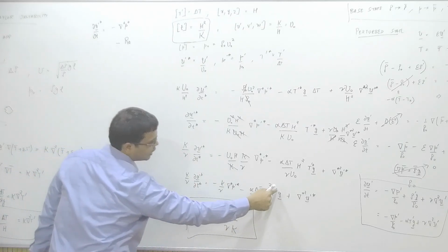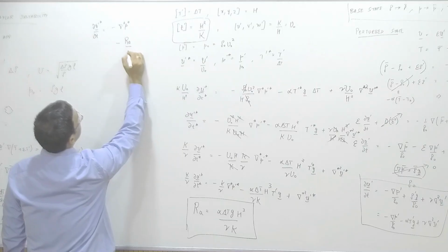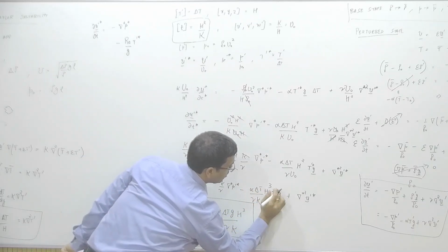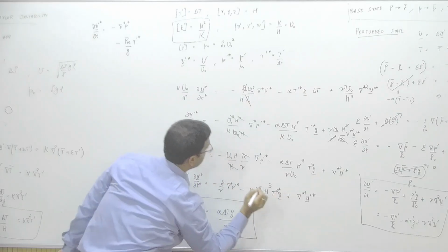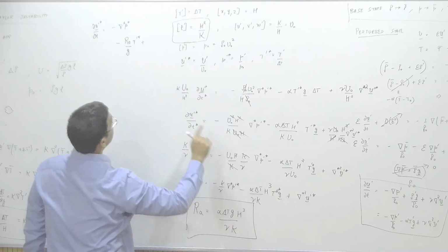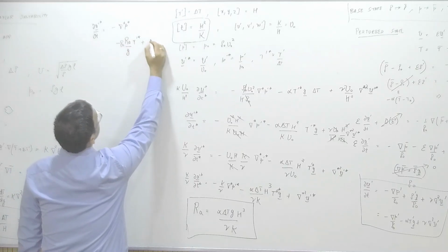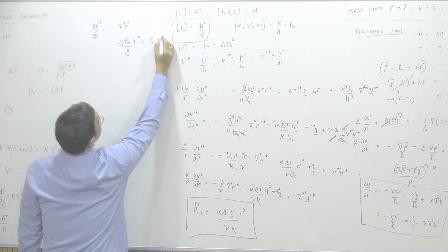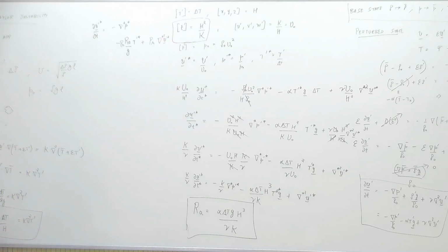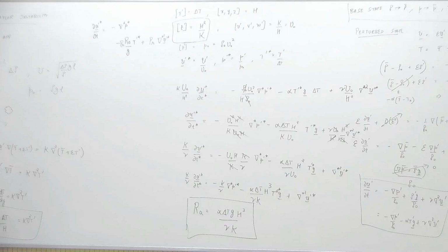Okay, so technically this term that you see here is Rayleigh by g, and then a t prime star, plus a nu by k, since we are multiplying with nu by k. So Prandtl number also appears here, and then a Prandtl number del star square u prime star. And this is the final dimensionless linearized momentum equation that we get.